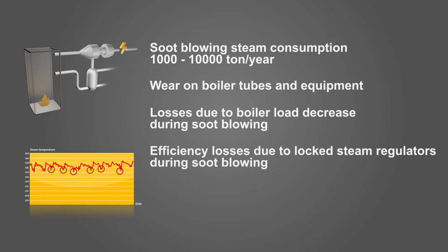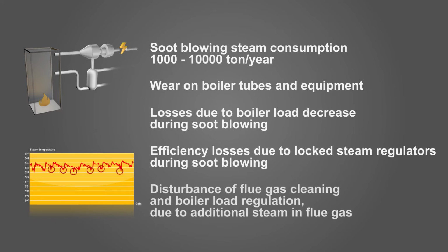Efficiency losses. Steam regulation must be locked during soot blowing. Disruption of the boiler flue gas cleaning and subsequent load regulations. Soot blowing is not cheap, so we do not want to spend more time and steam on soot blowing than necessary.